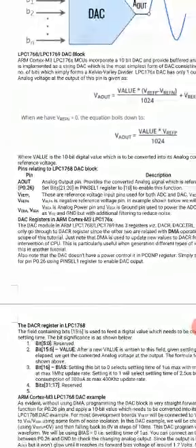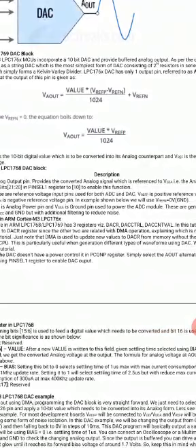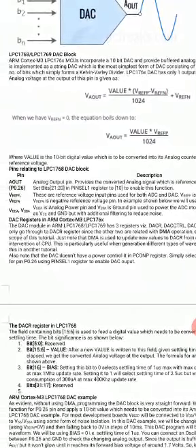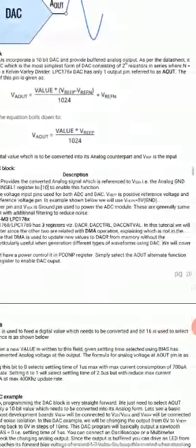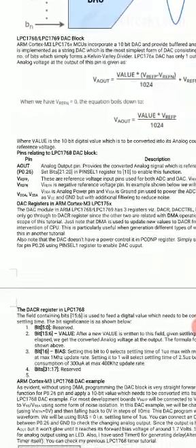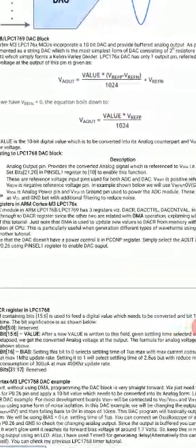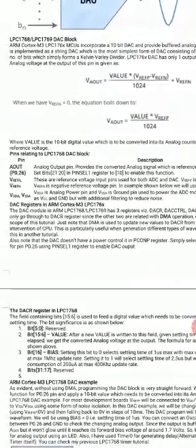Okay, so V reference P and these are the reference voltage pins used for both ADC and DAC, and usually it is VCC. V reference N is the negative reference voltage, usually kept at 0 volt. Then we have VDDA and VSSA. These are the analog power and ground pins to power the ADC module, which has resistors connected in series. That module is powered using VDDA and VSSA, usually connected to VCC and the ground.